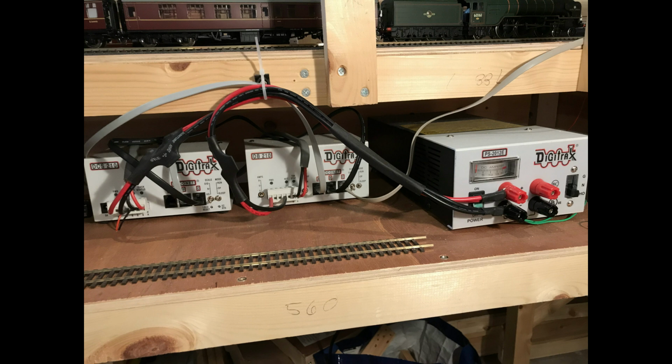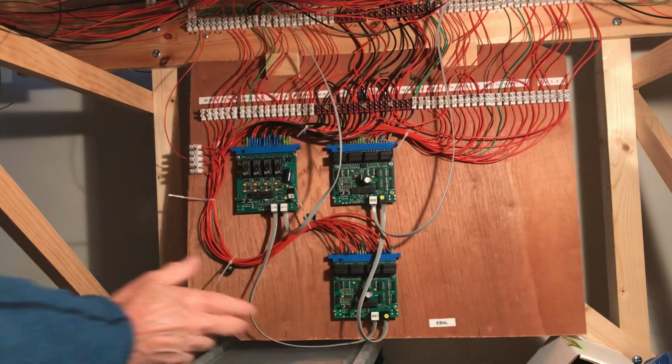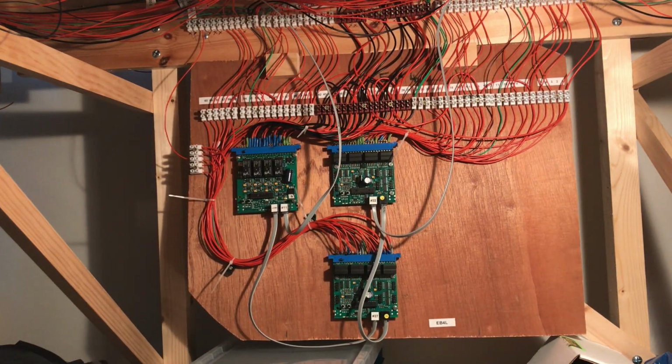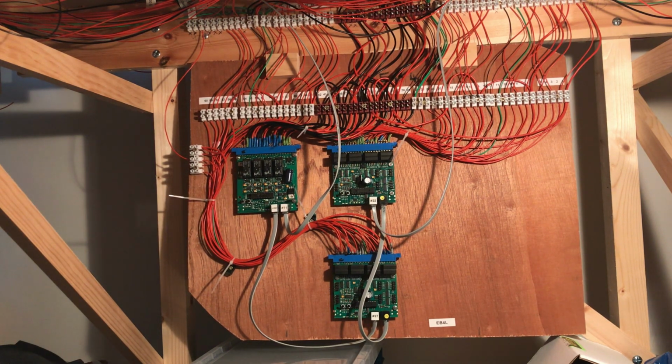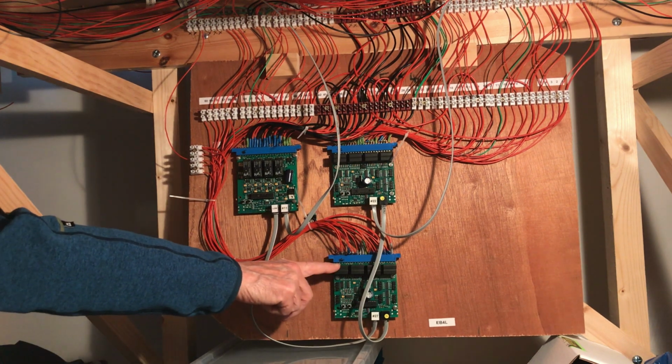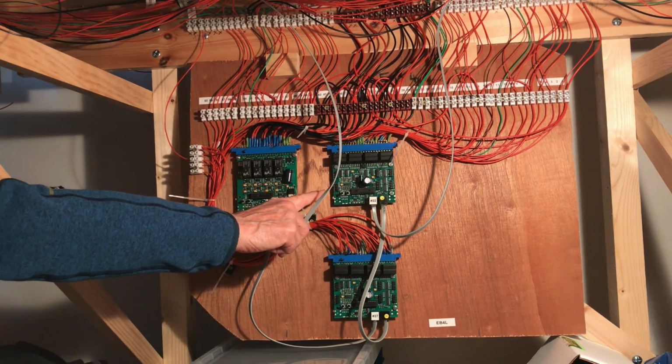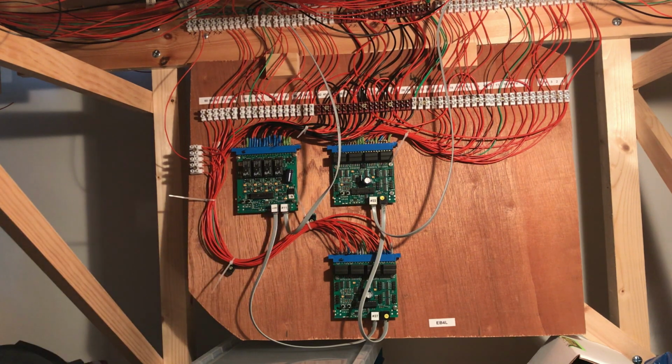On the hardware side, I'm using generally Digitrax equipment with 2 power districts, that is a separate booster for each level. Each booster feeds through a PM42 module to allow separate powered sub-districts and also manage the polarity changeover on reversing loops. Track power then feeds through a Digitrax BDL168 track occupancy sensor which detects current draw in a track section. Each one of these units can monitor 16 track sections.